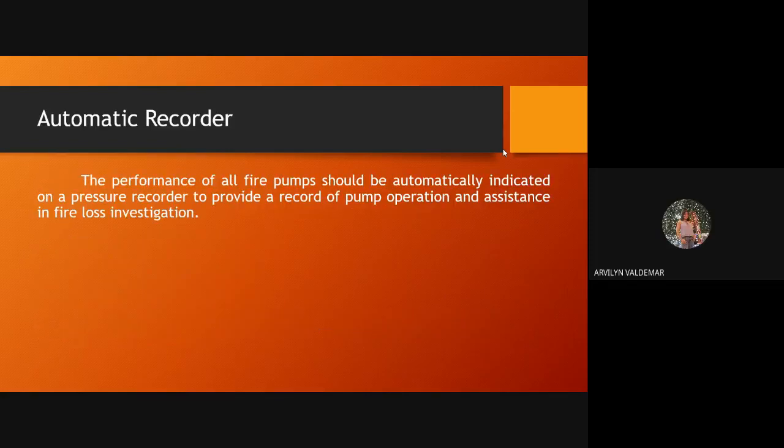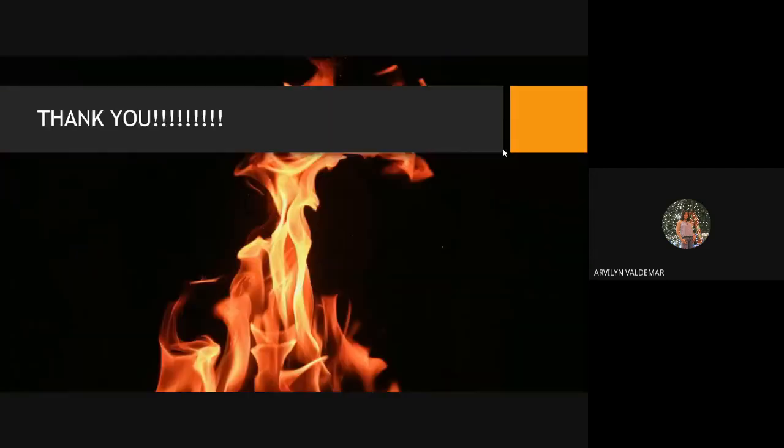So, for automatic recorder, the performance of all fire pumps should be automatically indicated on a pressure recorder to provide a record of pump operation and assistance in fire loss investigation. That's all, sir.